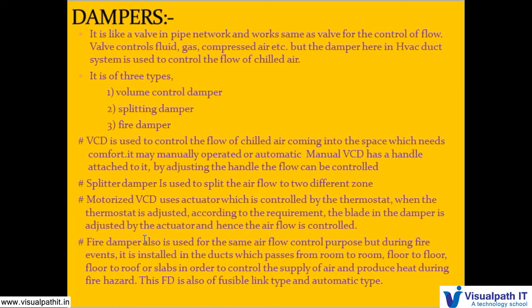Fire dampers are installed in the duct wherever it is crossing the walls. If there is a wall, it is a partition between two spaces, right? The fire in space A should not pass to space B. So, these fire dampers are placed for such a purpose.